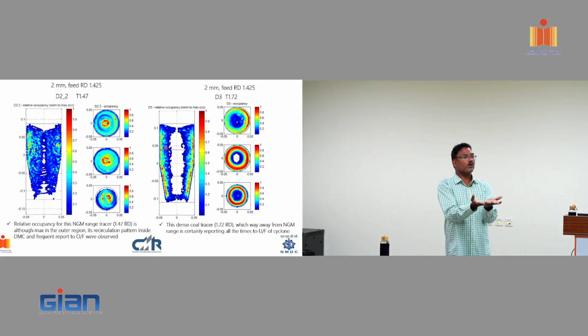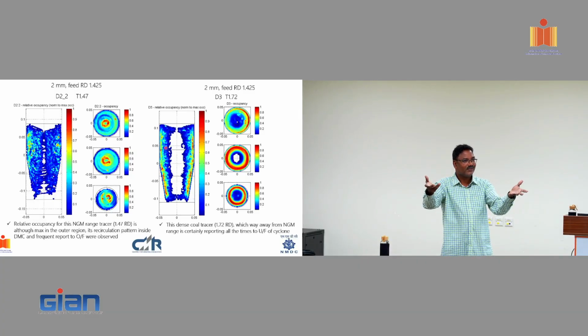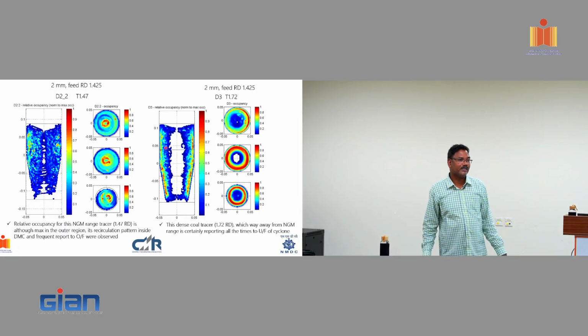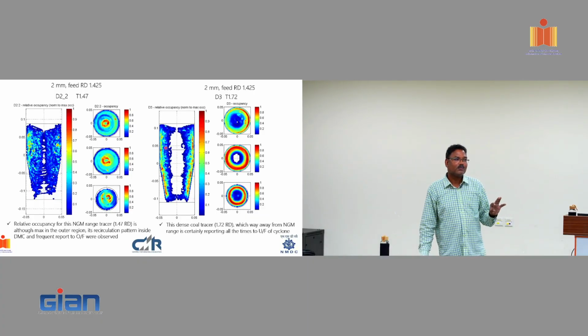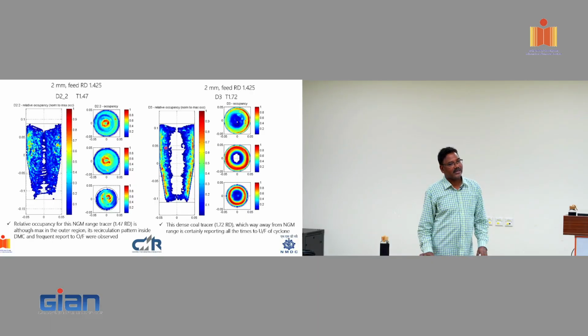So they subjected it to jigging, and they had to do all that on the ship itself. You cannot bring anything from the sea to the shore. So they were establishing a mobile plant. It's like the way we extract petroleum, right, on the ship itself. And then they separate and bring the material to do downstream processing of further dense medium, all of that. So it involves multi-component separation in the way we understand. But otherwise, the basics are still very important for us to make our design choice.